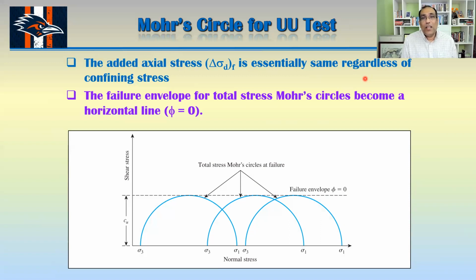If the effective stress on the soil is not changing, the axial stress or deviator stress will be the same in each case when you change your confining stress.